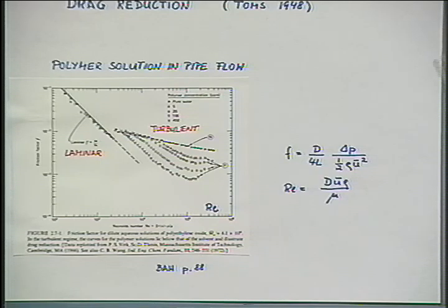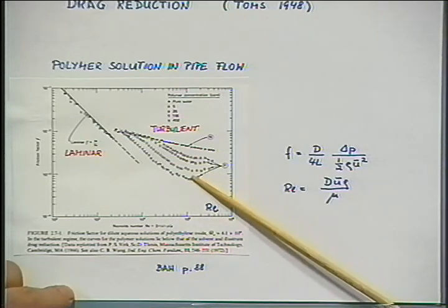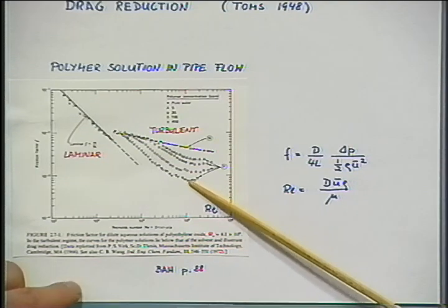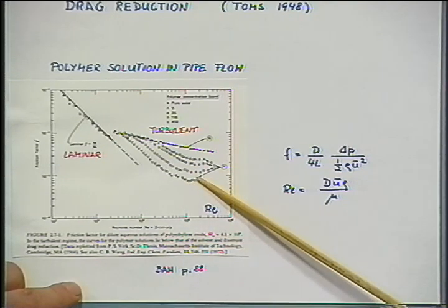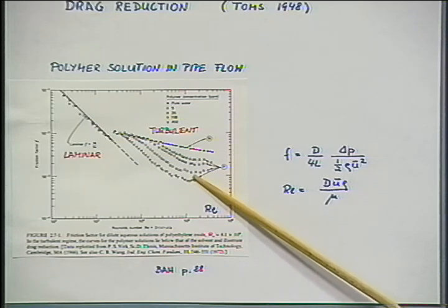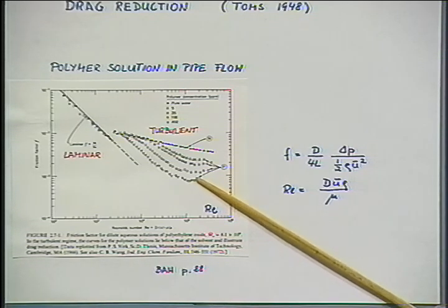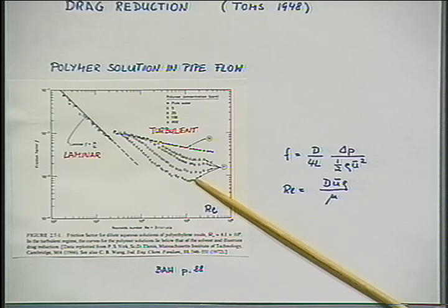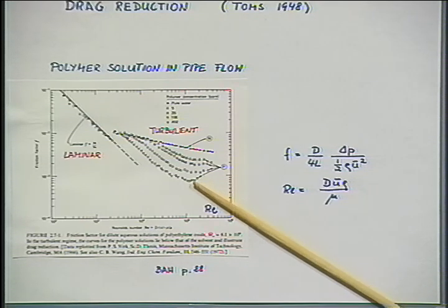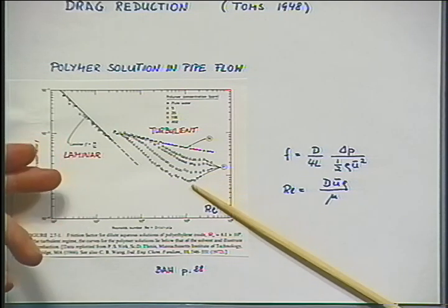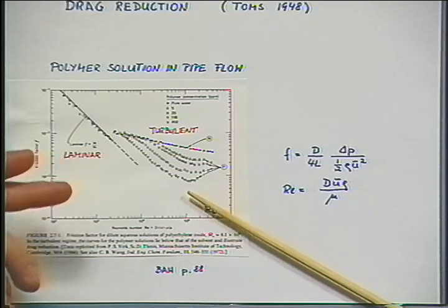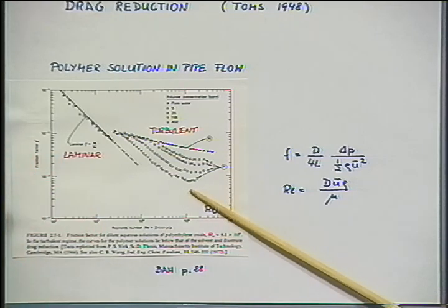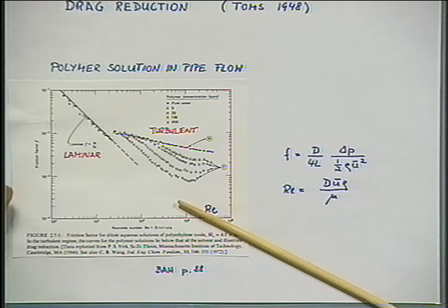And this phenomenon is used by firemen sufficiently. They have a pump, and sometimes the water pump is too small to squirt fast or far enough into a fire. They have to move very close. But if they add some polymer to the water, and they do this quite often, then they squirt further with the same pump. They call it rapid water.